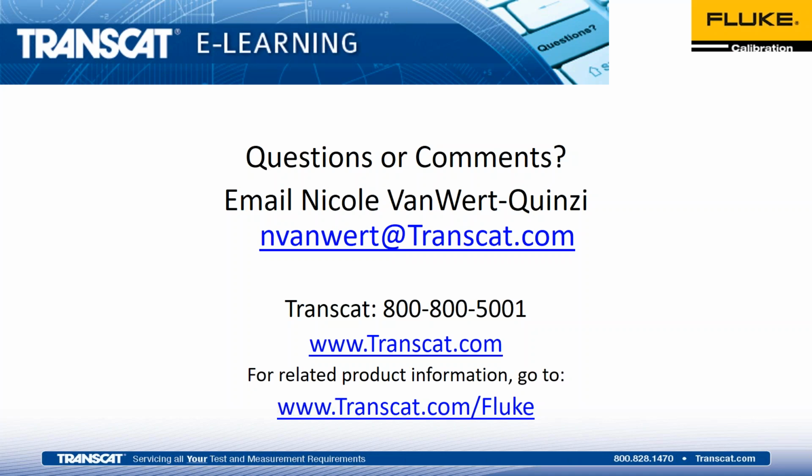Okay, why use the 9190A over a temperature bath? Again, it's portability. A lot of folks will use the dry wells over baths because they're working in situations where they have to move around a factory or they're moving above elevation. A lot of folks don't want hot or cold fluid above particular applications.